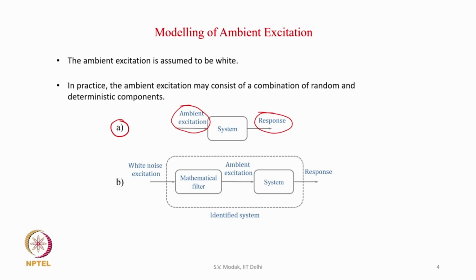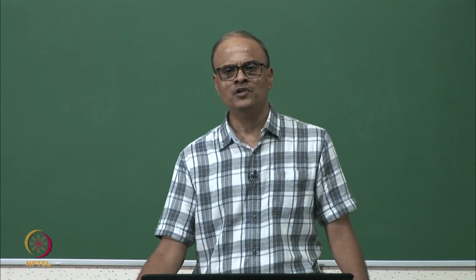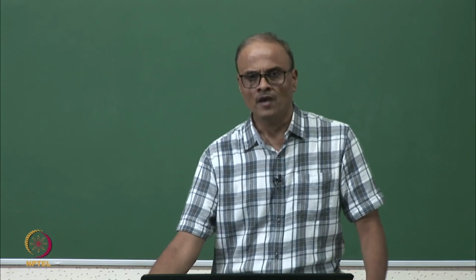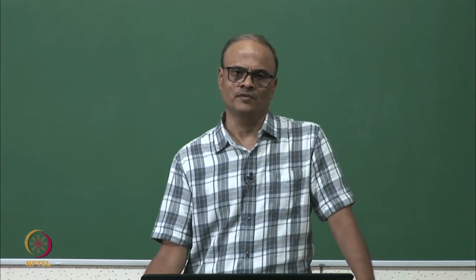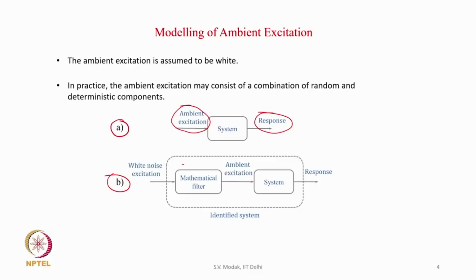Now, in part B of the figure, what we see is the implication of the assumption of white noise input acting on the system in case of operational modal analysis. Operational modal analysis assumes the ambient excitation acting on the structure to be white. So, this assumption amounts to existence of a mathematical filter before the system. You can see this is the mathematical filter which converts the white noise excitation into the actual ambient excitation which acts on the system and generates the response.